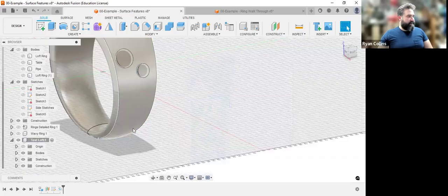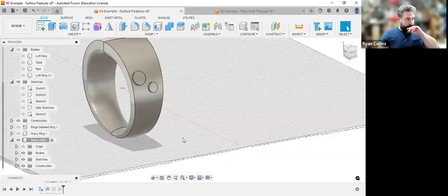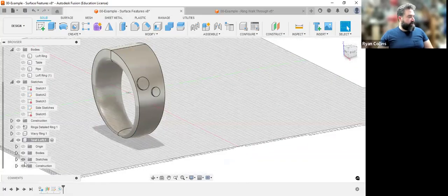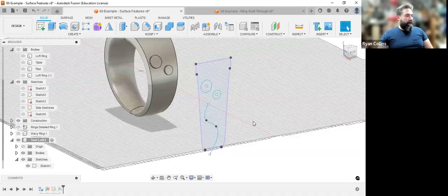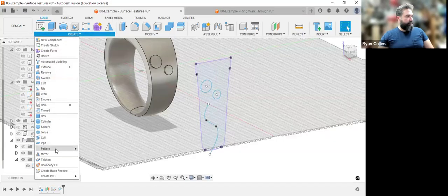But what if I want to add something along the edge, the side there? Well, that's where I use this sketch, but I can't just emboss a straight line. Obviously, you could go back into the sketch and add some dimension to it, make it wider. So you would emboss a standard sketch profile, something with dimension. But I want to show you how you can use those same tools, sketch and project, to make a line on the surface. This is really helpful if you're wanting to use another tool, pattern on a path. I'll show you how that works in a moment.